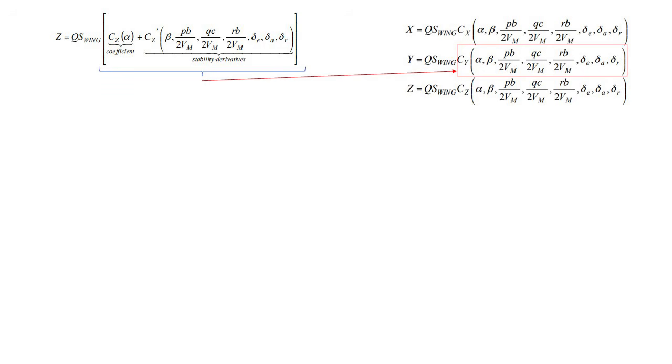The side force and rolling moment equations follow the same structure as the normal force and pitching moment equations. I won't go into too much detail about the side force stability derivatives, but I can summarize this by saying that a rudder and fin displaced from the yaw axis of the aircraft during a side slip causes local incidence and therefore side force, and a similar thing happens with the rolling moment since the CP of the fin is generally displaced from the roll axis.